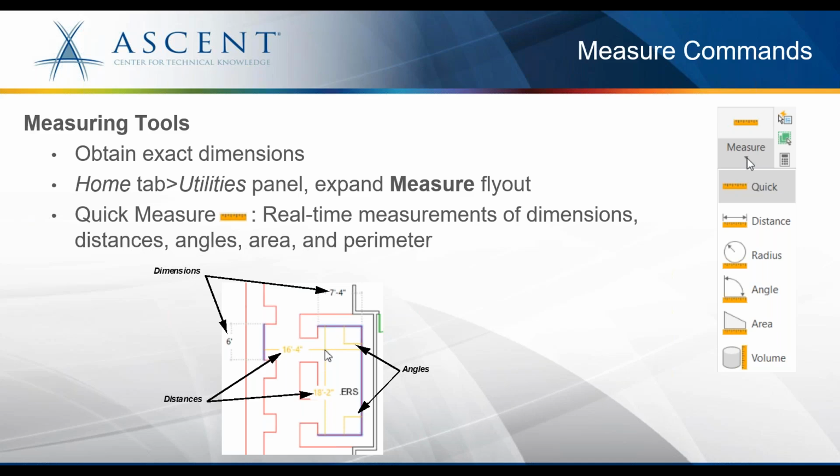So these measure tools are located in the Home tab, Utilities panel, where you can expand the measure flyout. You can see that on the screen on the right hand side, and all the measure tools are listed there.